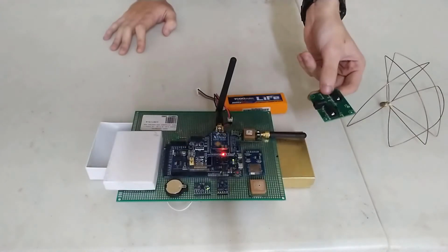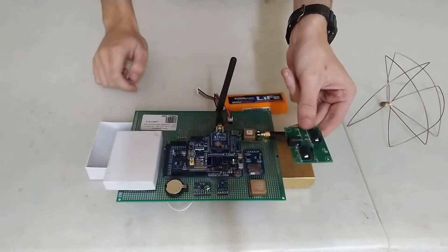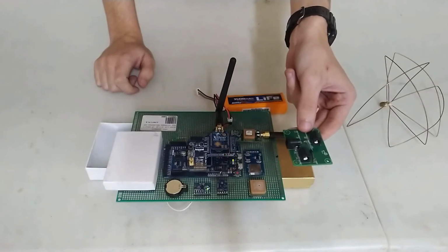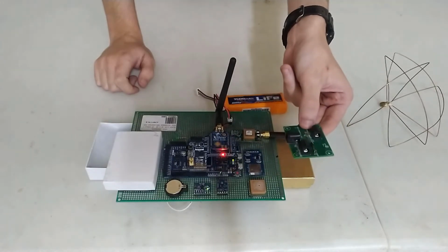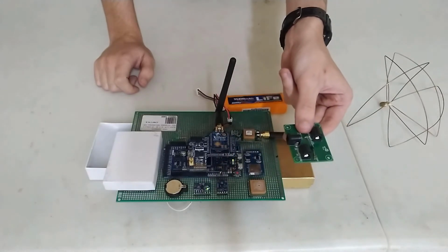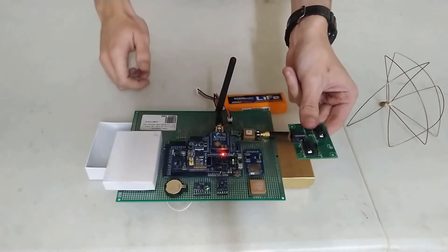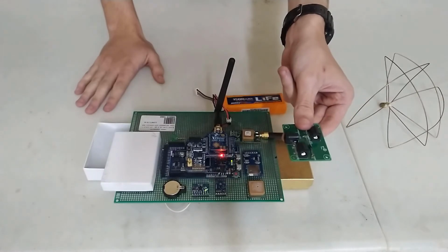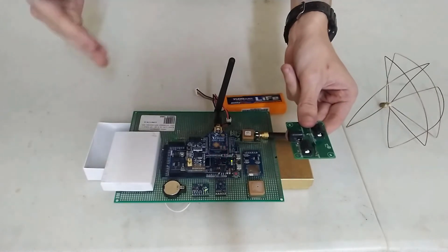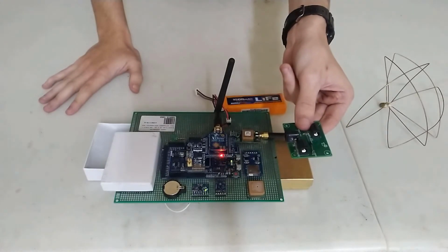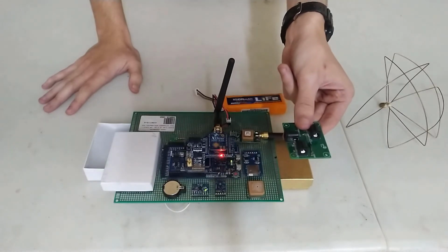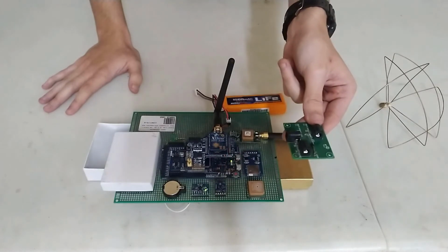On the real field, we use one of those, which is a board we also make with a diode, so we can plug in an external battery to prevent the internal battery from draining out before we launch the rocket. The diode is to not allow the internal battery to charge the external battery, so it's a one-way only power entry. And as soon as we unplug the external battery, it switches automatically to internal power.